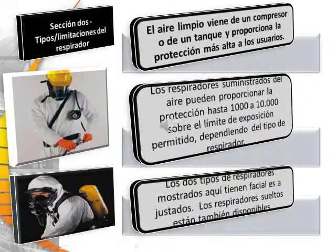Clean air comes from a compressor or tank and provides the highest protection to users. Supplied air respirators can provide protection up to 1,000 to 10,000 times the permissible exposure limit, depending on the type of respirator. The two types of respirators shown have tight-fitting facepieces. Loose-fitting respirators are also available.